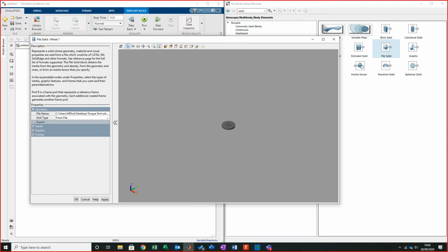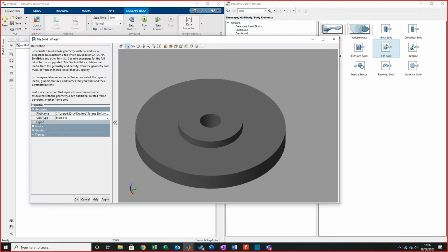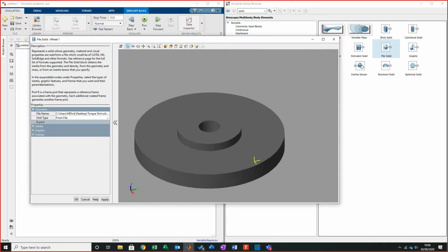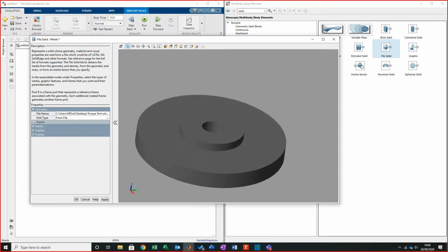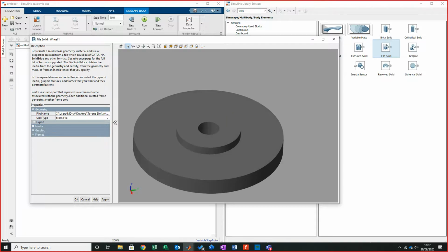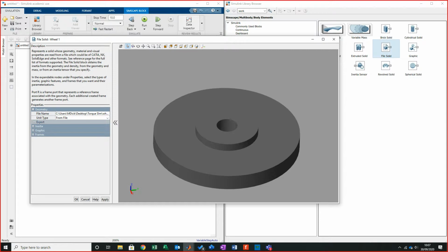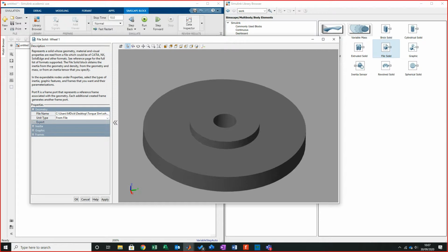And then I'm going to use my zoom to fit, and there is our wheel. Now, what's the most important thing I need to know is, where is that bloody datum? So if you look on the datum, the good thing is whoever drew it correctly. You can find sometimes that if that hole is on the y-axis, you've got to spin it. Granted, I did draw it like this to make this particular set of notes easy to start with, because I will be giving you ones where the geometry is all over the place.